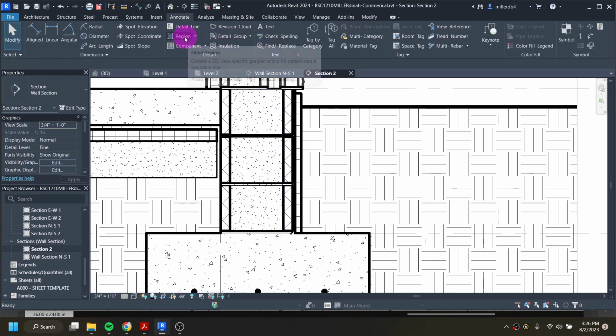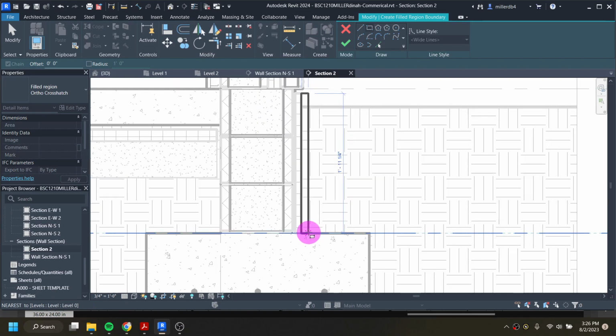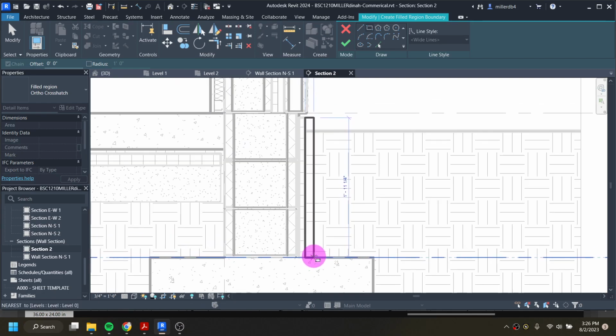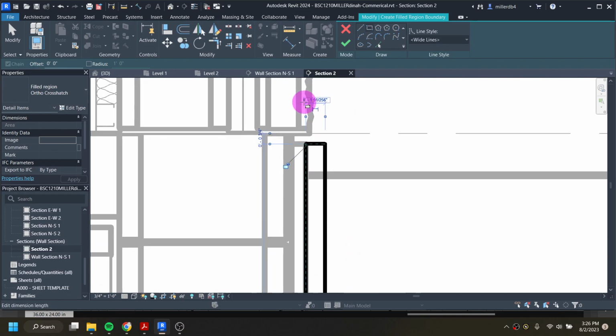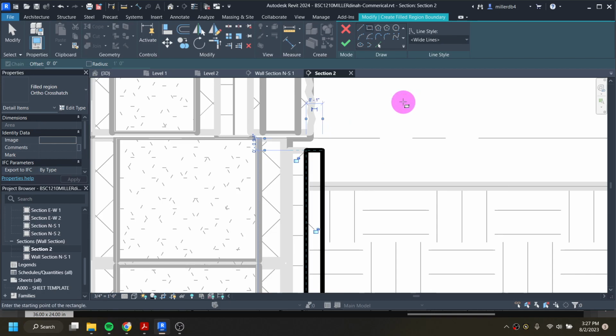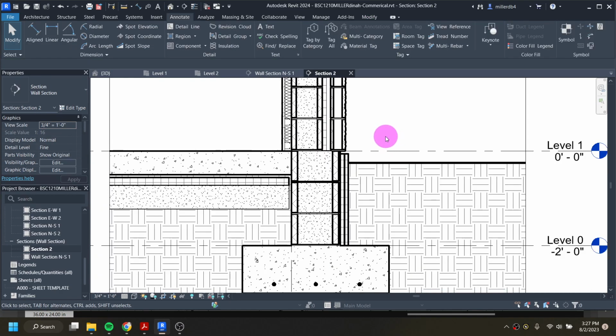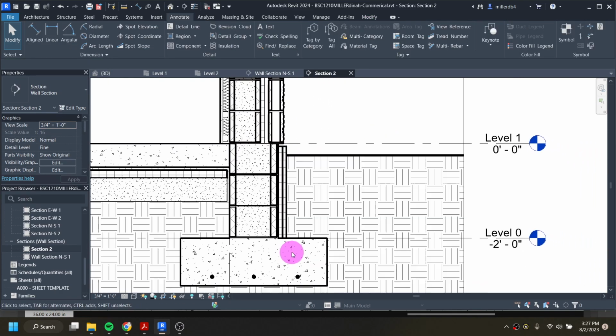So I'm going to region on that point. I'm not in the rectangle tool. I'm still going to keep it on wide lines. Straight down. After I place it, I can then edit this witness to also make this one not 1 foot, 0, 1, 1 inch. That way I have those 2 boxes there. And then I can add in my French drain.